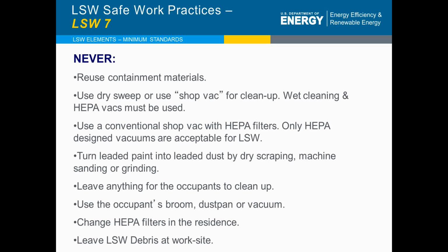We're not reusing our disposable suits. We're not dry sweeping dust. We're vacuuming that with a HEPA vac and doing wet cleaning. We're not leaving debris at the work site.